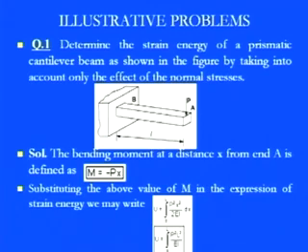Now within that particular frame of mind, we have the total strain energy. If we integrate that part, we have U equals P squared L cubed divided by 3EI, because the integral of x squared dx will be x cubed by 3. We can simply replace that part, and the total terms are like this. So we have the strain energy in that.